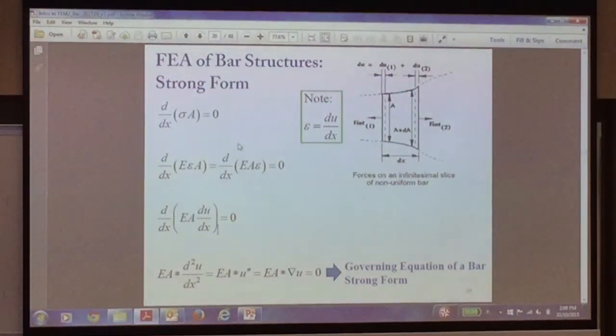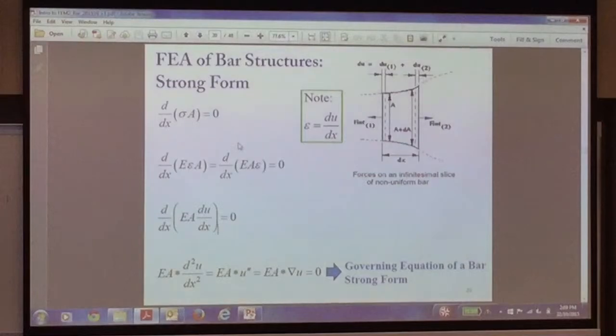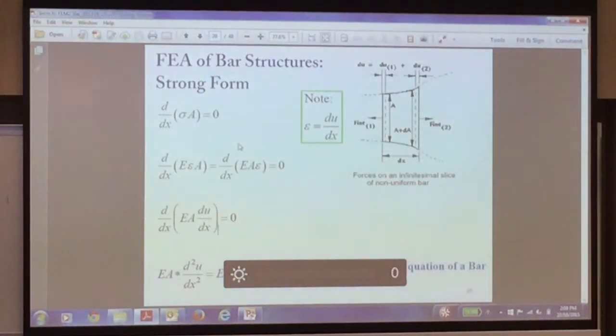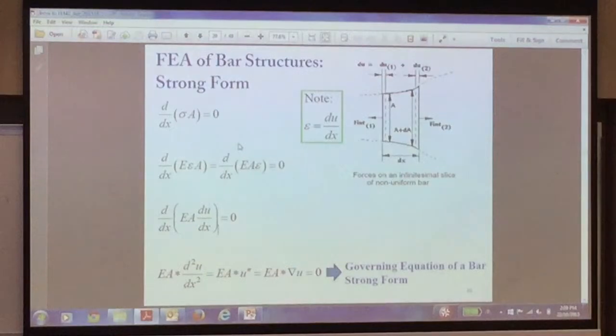You draw your geometry, apply the load, apply the boundary conditions, run it, and you get your results. You get the stresses, the strains, the displacement, compare it with the material properties, and there you have it. Very straightforward. The only thing is that to strengthen your knowledge or your application of finite elements, you have to go back to theory because you have to know its limitations.